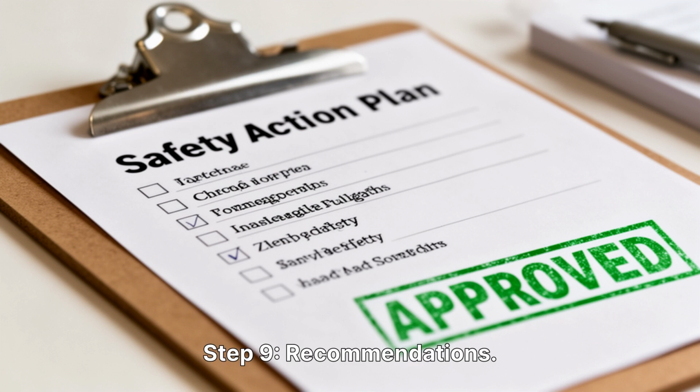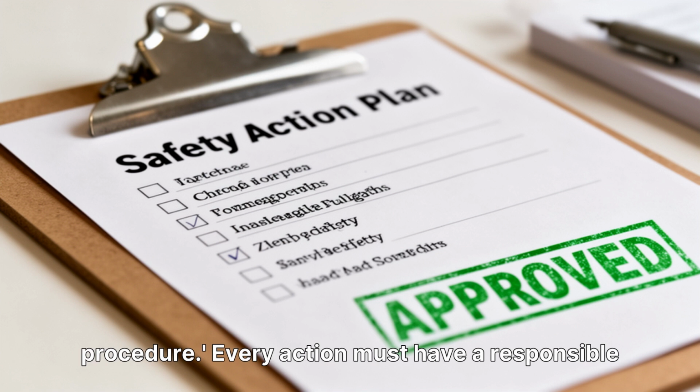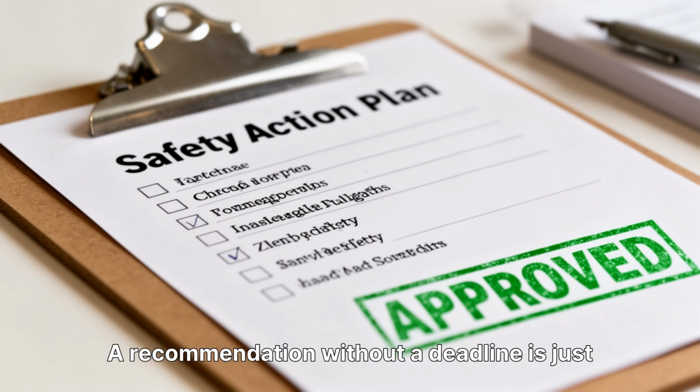Step 9, recommendations. If the risk is too high, we recommend action. Install a low-flow trip. Update the operating procedure. Every action must have a responsible person and a deadline. A recommendation without a deadline is just a wish.